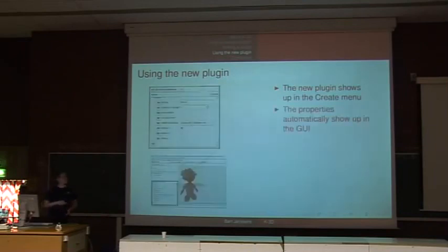Again, after creation, the properties panel shows up, and we find our three properties as we declared, also automatically taken into the user interface, with the first one set default true, the others default false. Now, nothing is happening yet. We still have our previously loaded mesh, but it's unaltered because we haven't set the input yet. In order to do that, as you can see, there's no possibility to enter a value or anything. We have to click the connect button.